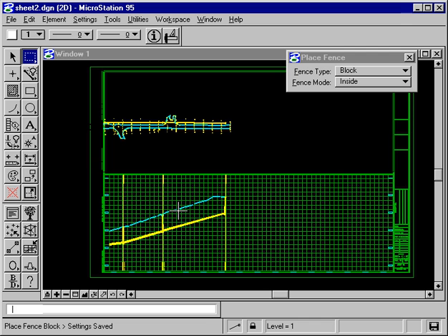The principle of Splash with Ripple-Thru applies to multiple drawings all attached to the same database. So we've been able to get an initial design and go ahead and create the plan and profile construction sheets without it being the very last thing we do. So if we have to make changes, then we're not forced to recreate all these sheets after the edit. So these sheets will automatically update themselves. So Ripple-Thru applies to all the MicroStation design files attached to one database.